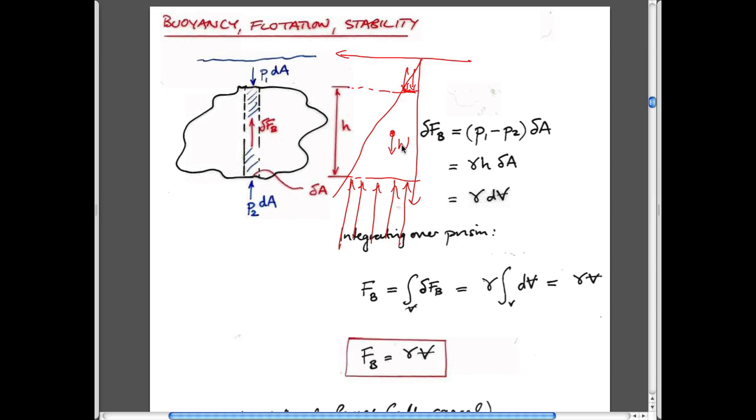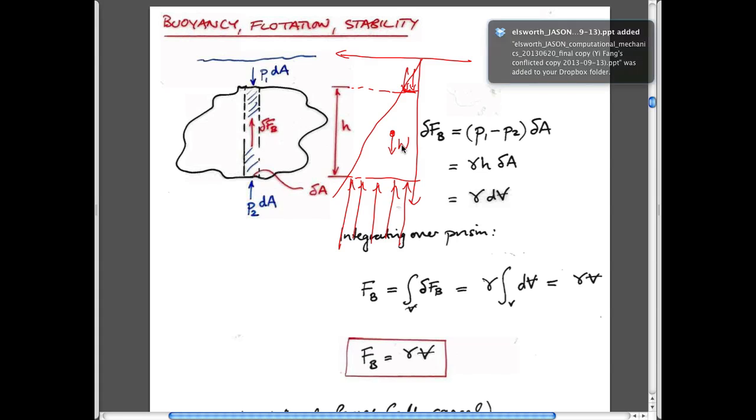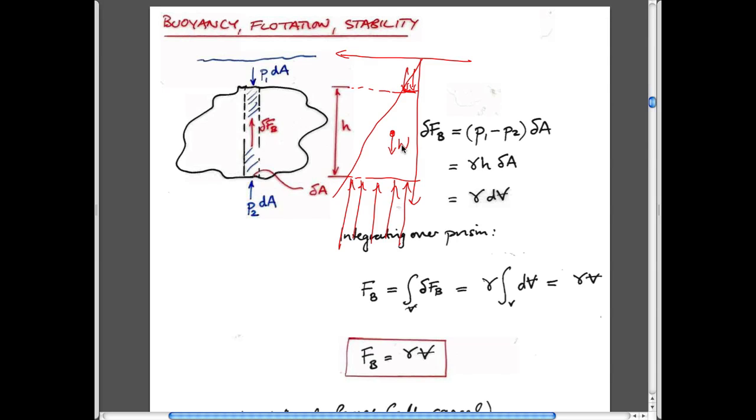Same as a ball, right? It has some weight attached to it. There's no force applied to the top of this ball, but clearly there's a force I have to apply on the bottom of this to keep it held up. The rationale for that is that it's this weight which is the reason for this pressure, and so they exactly balance each other so they're in equilibrium. If you remove this weight from the interior by just carving out a hole, then all of a sudden you have an excess pressure on the bottom of this thing, and that's what buoyancy is. That's why things want to rise in water.